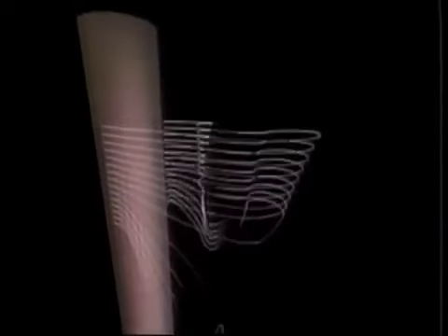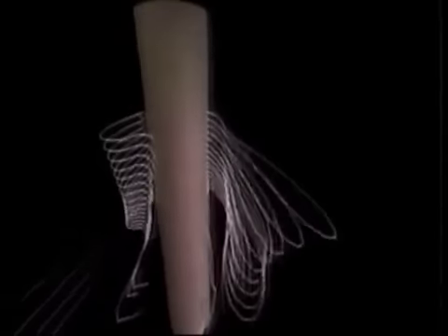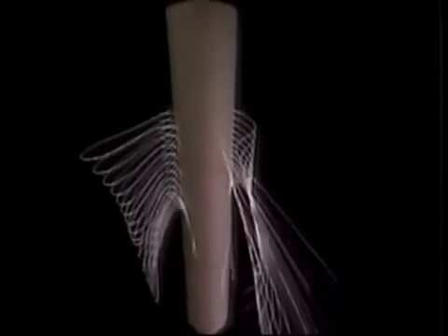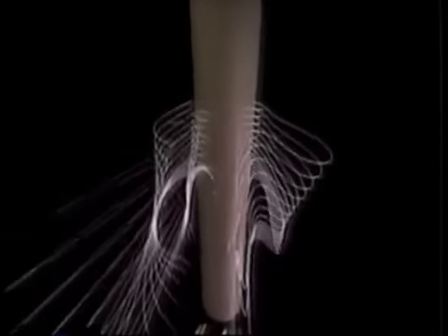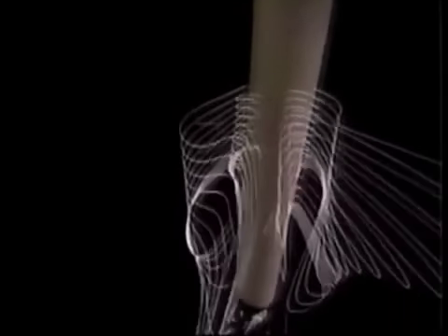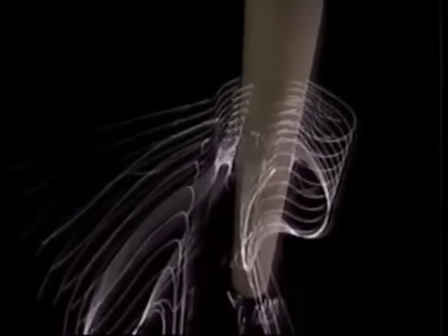Some of the most challenging computational aerodynamic problems involve three-dimensional flows that change over time. Here we see non-periodic vortex shedding past a slightly tapered cylinder. The flow is visualized by placing a line of virtual smoke emitters along each side of the cylinder. The vortex shedding process can be clearly seen. Smoke circulates for a while near the cylinder and then breaks off and travels downstream.